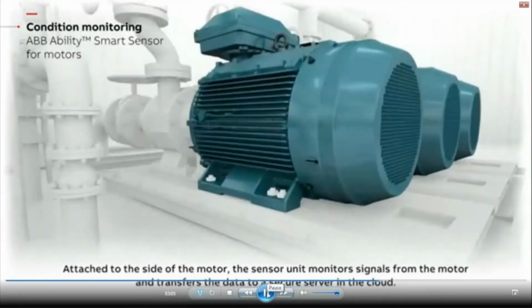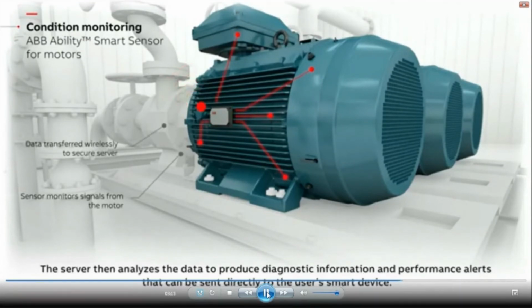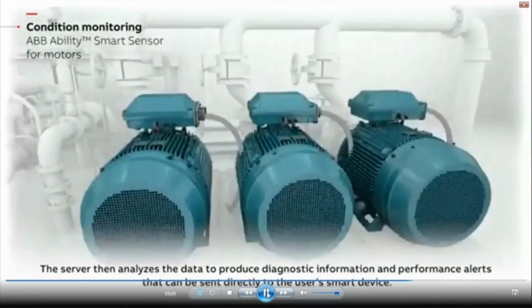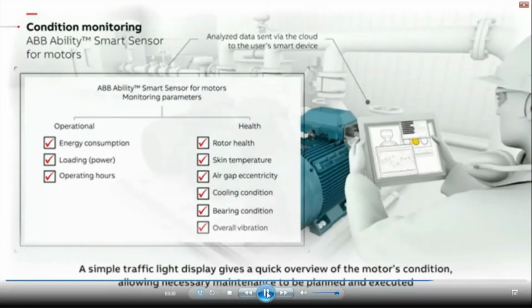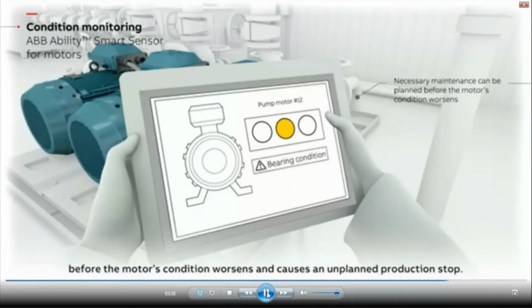Attached to the side of the motor, the sensor unit monitors signals from the motor and transfers the data to a secure server in the cloud. The server then analyzes the data to produce diagnostic information and performance alerts that can be sent directly to the user's smart device. A simple traffic light display gives a quick overview of the motor's condition, allowing necessary maintenance to be planned and executed before the motor's condition worsens and causes an unplanned production stop.